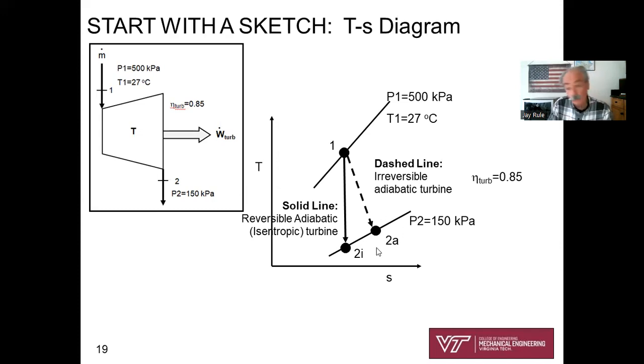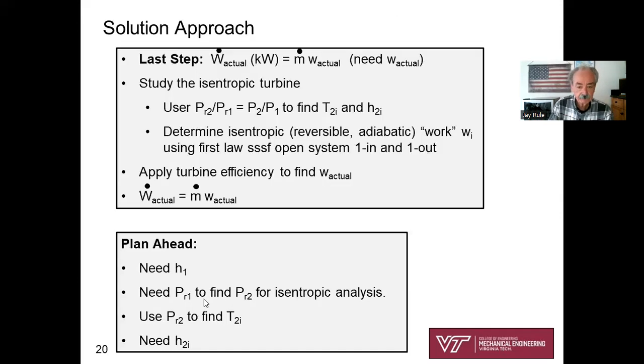We're going to the right, since it's adiabatic, S2 is going to be bigger than S1. S2 actual will be bigger than S1 because of the second law. Okay, and that's a decent sketch. That's a professional quality looking sketch for this problem.